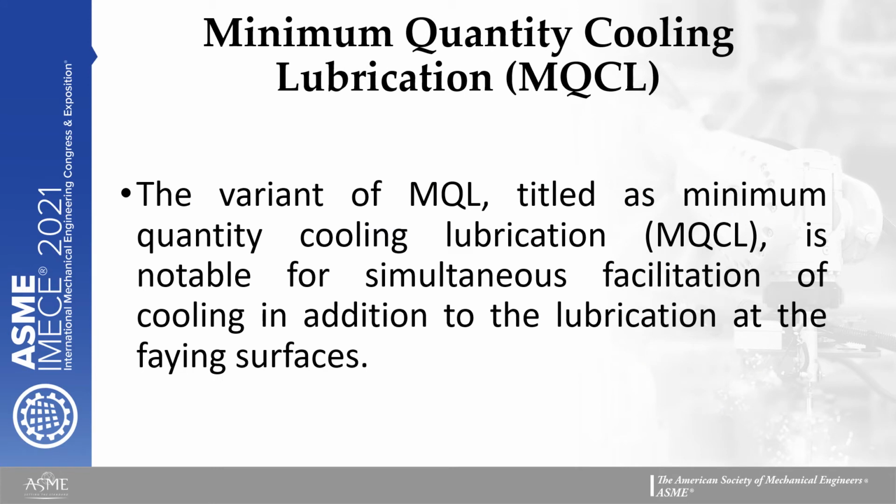The conventional MQL technique is referred to as a lubrication technique. Because it is a lubrication technique, it takes care of the friction part during the machining operation. Another variant of MQL is called MQCL, that is, minimum quantity cooling lubrication, where sub-zero temperature air is mixed in the MQL, and the sub-zero temperature air takes care of the cooling part during the machining operation.